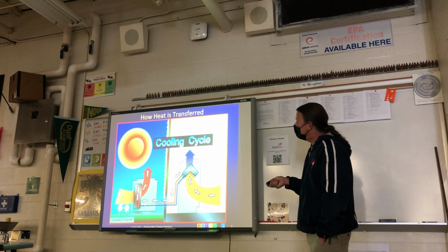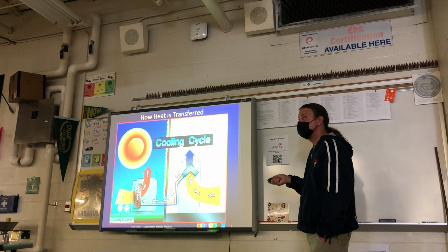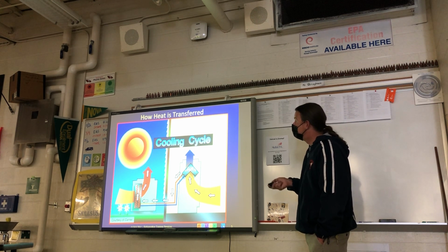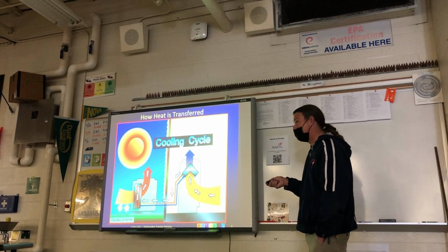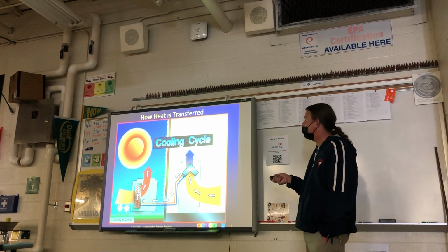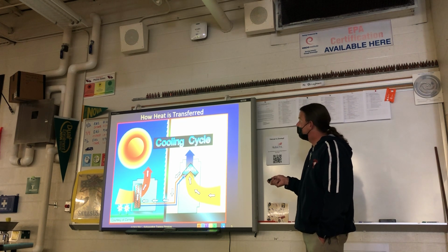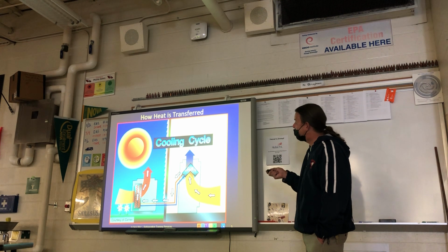What 2 are going to be out here? Outside. Oh, it's an air conditioning unit. So that's our condensing unit. And then I heard somebody say evaporator, so that's in here. So the metering device is probably really close to the evaporator on this side. And this is a split system.